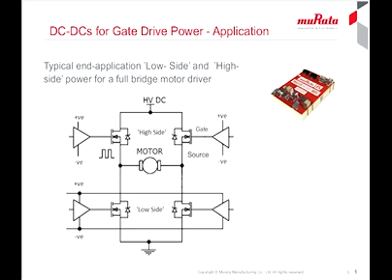This power rail, labeled HVDC, is sometimes not so high. It might only be 24 volts for a low voltage motor, and in this case the DC-DC converter is not normally used. However, the DC-DC becomes the right solution when the power rail is hundreds of volts or higher. Typical values seen are 380 volt DC from a 230 volt AC main, rectified and power factor corrected, or maybe 1000 volts from rectified 690 volts AC, the common industrial power standard.